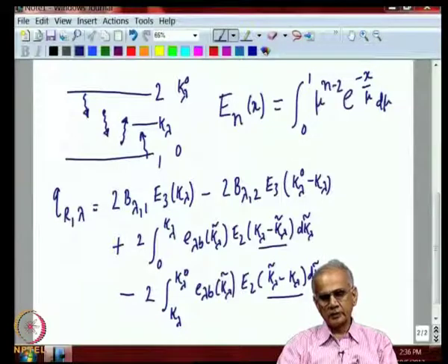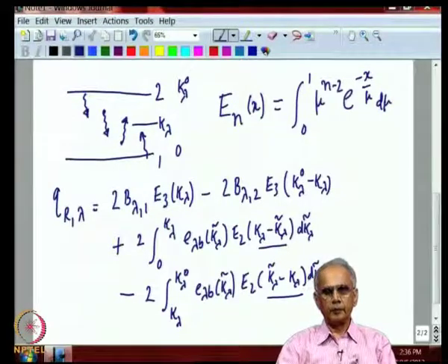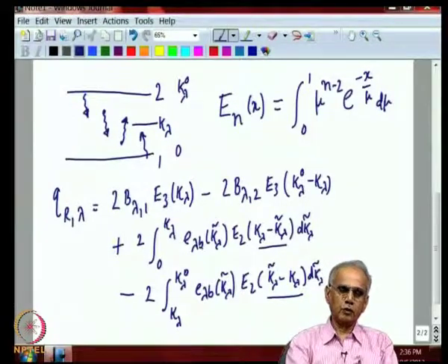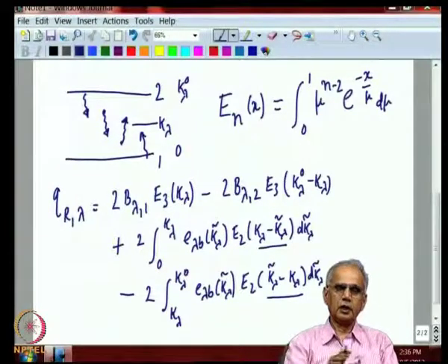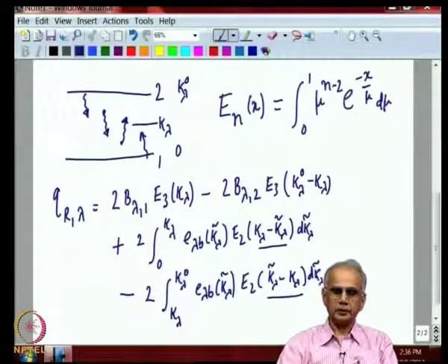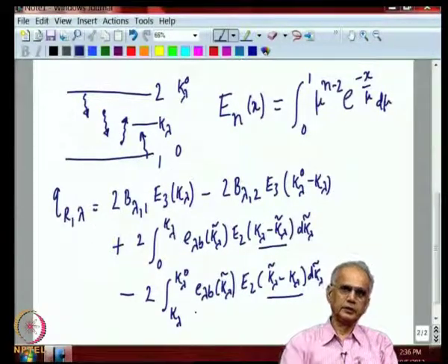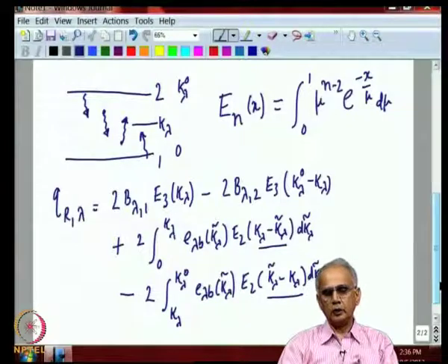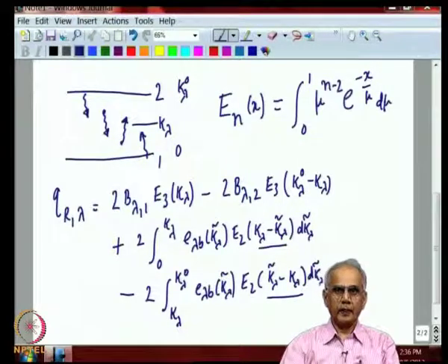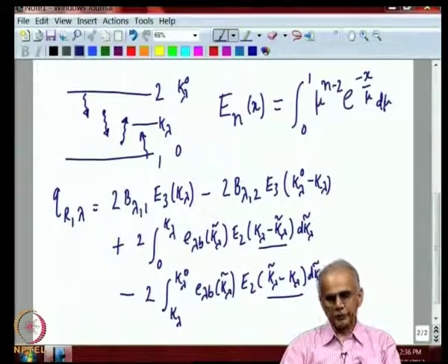In radiative heat transfer in gases, the problem has been more difficult because unknown temperature does not appear as a part of a differential equation, but as an unknown inside an integral. So, it is an integral equation here. So, we do not have as many techniques for solving integral equations analytically as we have for differential equations.